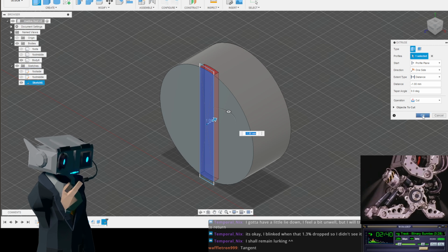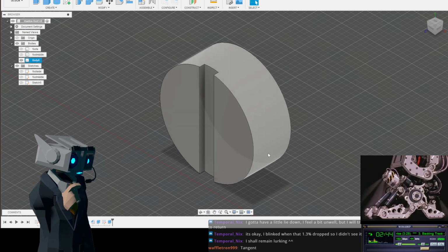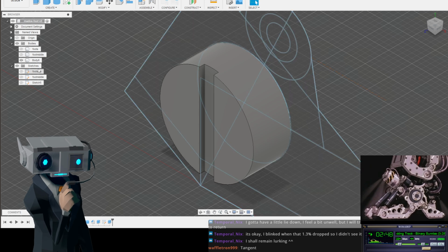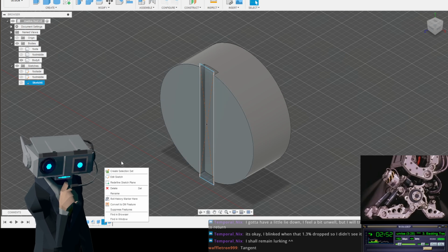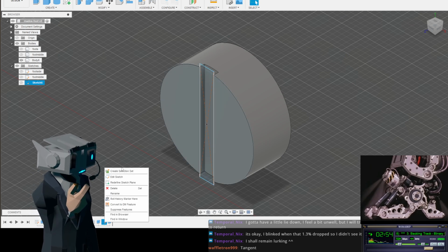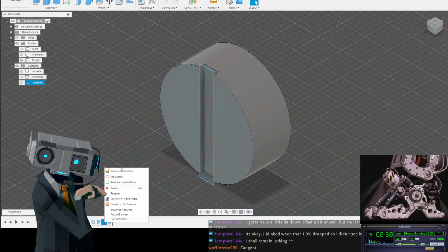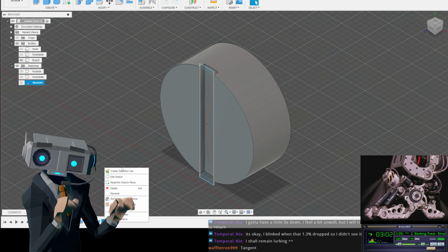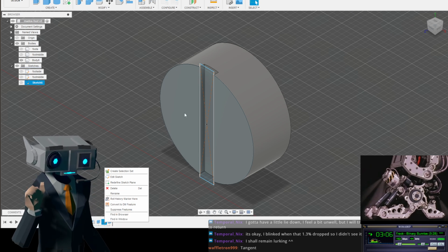That looks like it'll probably be enough. Now I could put in the two bolt holes while I'm here, I suppose. So what I should do is go back in here and edit this sketch again. No. We're going to put in all those little bolts and screws later, because we can just go into Maya, make one, drop them all into place, and use alignment tools for that kind of thing.